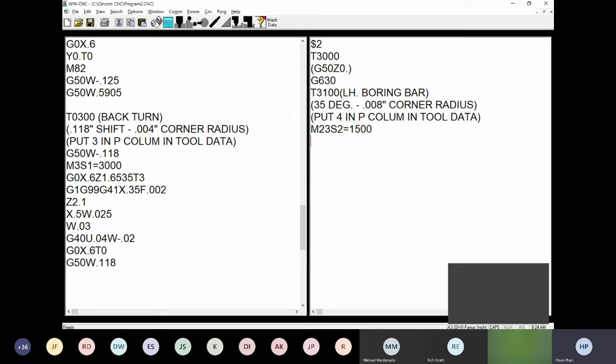Okay, we're going to use G96, so we're going to have to turn off the fluctuation for the sub spindle, which is M94. Give it the limits for the spindle, 4,000, and then G96 S900.